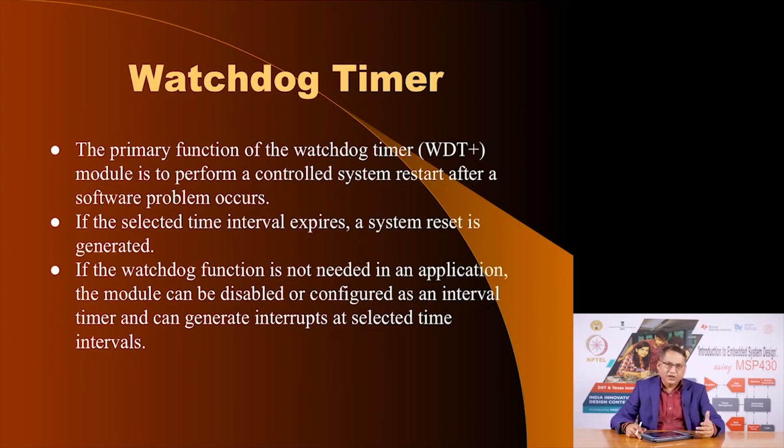Now, if you enable the watchdog timer, how do you ensure that it does not create a power up condition? You frequently reset the watchdog timer, because when you reset it, it will start from 0 again, it will count up, and before it expires, meaning before it overflows, it is your responsibility to reset it. In case you forget to do that, it will create a power up condition, and we will see later in a code how the watchdog timer can create a power up clear condition.